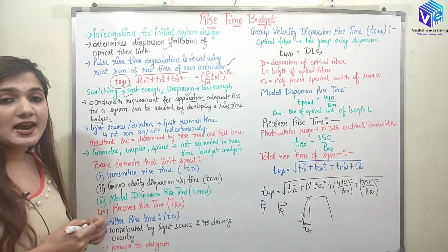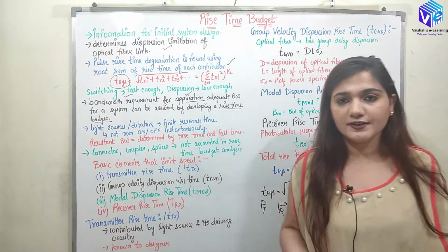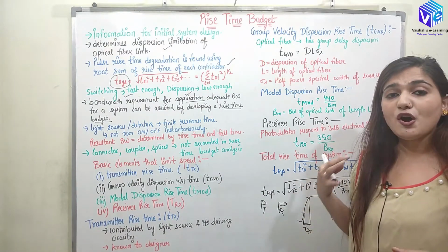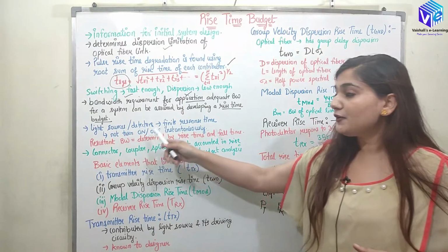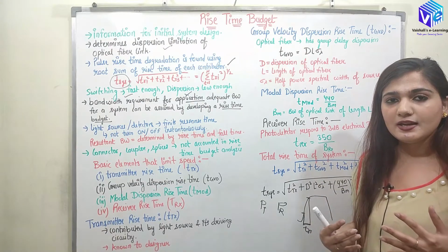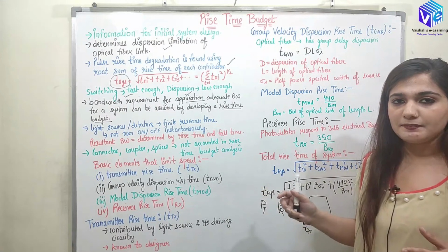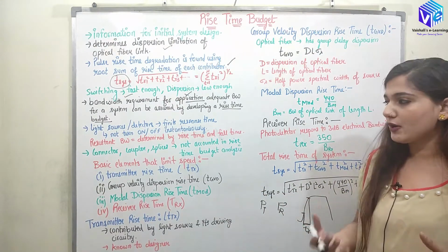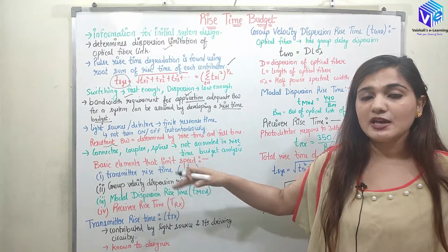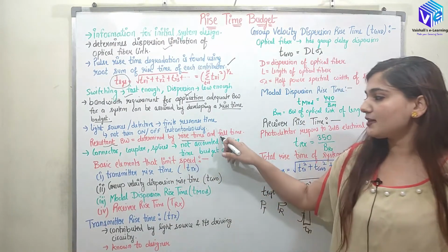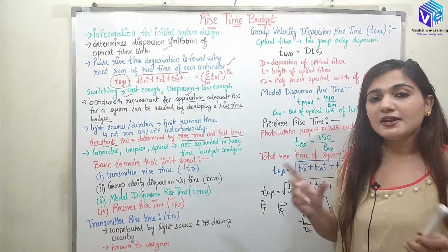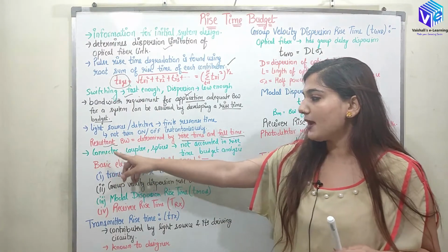So the light sources that we have or the detectors that we have are both having their finite response time, right? Because they are taking some time to turn on or off. The sources or detectors are not turning on and off instantaneously. So I require the finite response time. Again, it becomes essential to find out what is the response time. So the resultant bandwidth, because it is not turning off instantaneously either, is determined by rise time as well as the fall time. We should understand what is the rise time, what is the fall time. By having analysis of both of them, we can determine the resultant bandwidth.